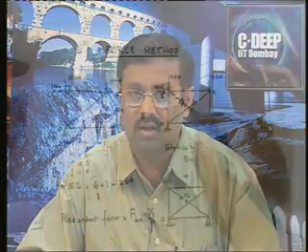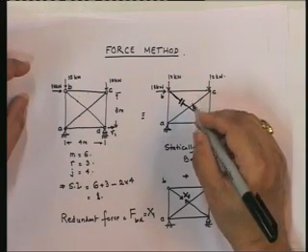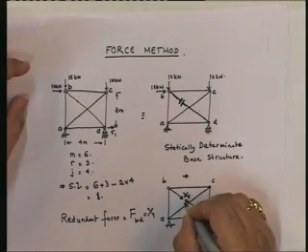Now how do I do this? See, this is a displacement. I need to find out a displacement. How do I find out a displacement using the method of virtual work? Use the method of virtual forces. Okay, what does it mean? Well, actually, since I am trying to find out the displacement at this point relative to each other, what do I do? I actually apply a virtual force at this point and compute the work done. Okay, and the total work done has to be equal to 0. That gives me the displacement.